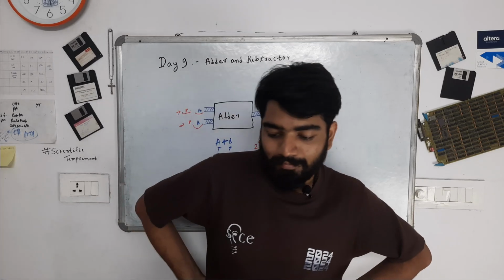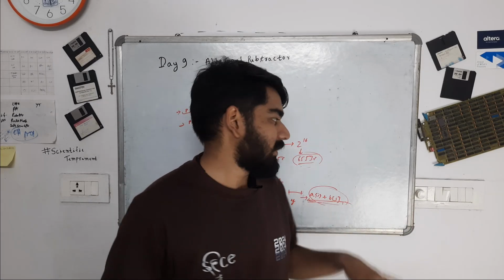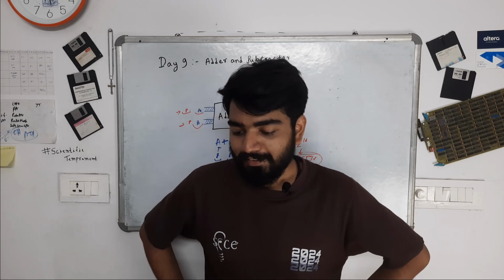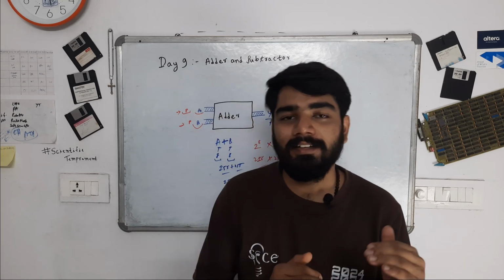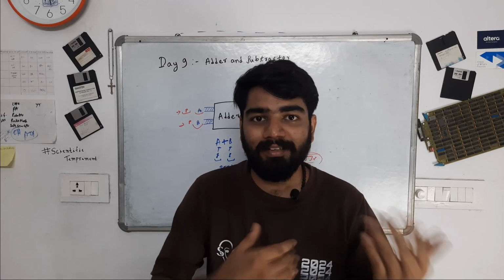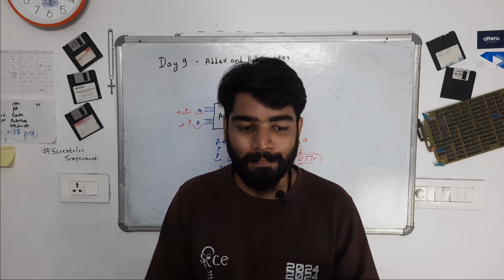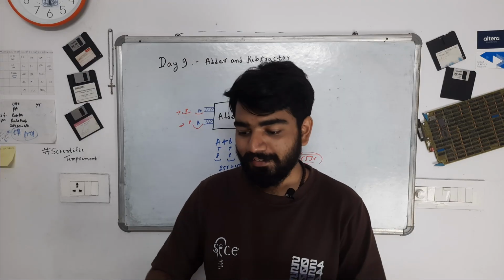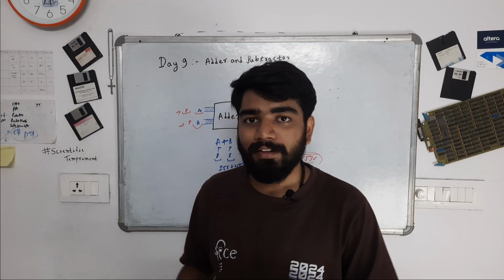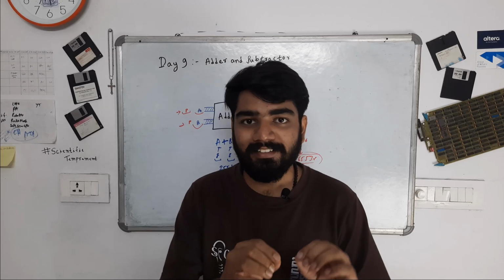I've shown you how you can exhaustively check the 8-bit adder, and I've also shown you how the subtractor is working and the common thing that you might miss when designing a subtractor, right? The signed and unsigned stuff. And I encourage you to do the same: do the subtractor and put it on the FPGA and check, and especially check the carry bit, okay?